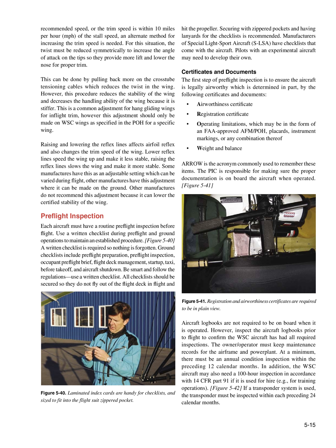Use a written checklist. All checklists should be secured so they do not fly out of the flight deck in flight and hit the propeller. Securing with zippered pockets and having lanyards for the checklists is recommended. Manufacturers of special light sport aircraft, SLSA, have checklists that come with the aircraft. Pilots with an experimental aircraft may need to develop their own.